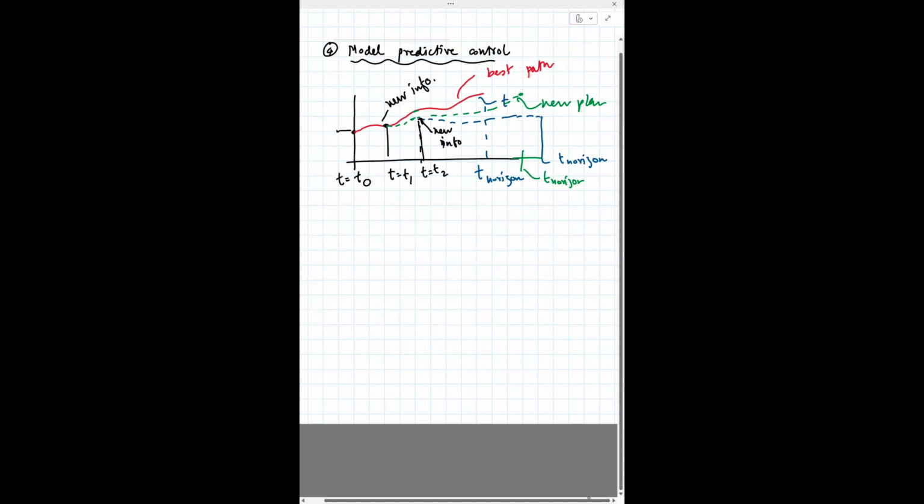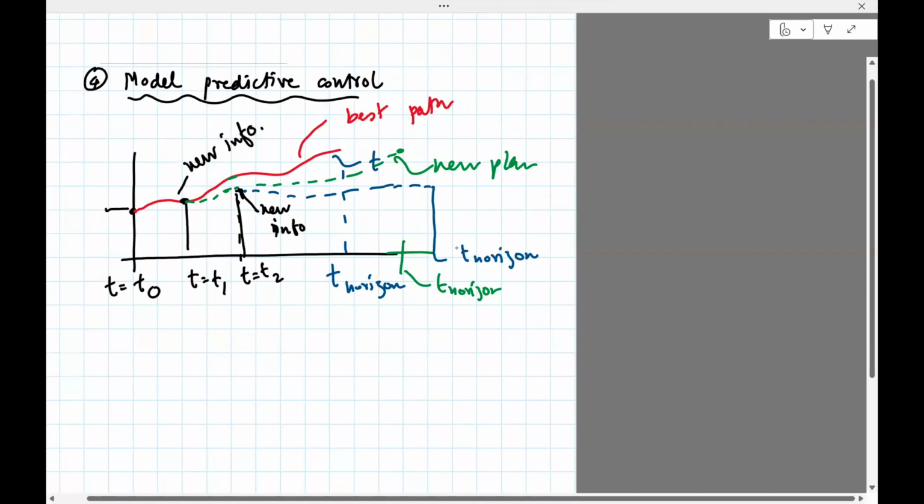So I did the same thing: the motion planning problem with model predictive control. The difference with DWA, the one which I talked about, is that DWA does rollouts for different v and omega and then finds the minimum. This one actually calls minimize. I decided to just use the angular speed, but you could change v and omega. You could have v and omega at different time intervals instead of having one for the entire horizon. So I just took the simplest case.